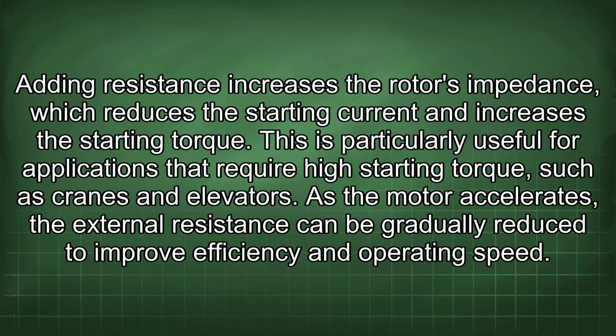Adding resistance increases the rotor's impedance, which reduces the starting current and increases the starting torque. This is particularly useful for applications that require high starting torque, such as cranes and elevators. As the motor accelerates, the external resistance can be gradually reduced to improve efficiency and operating speed.